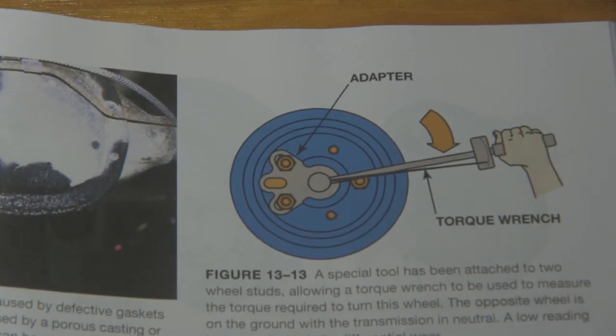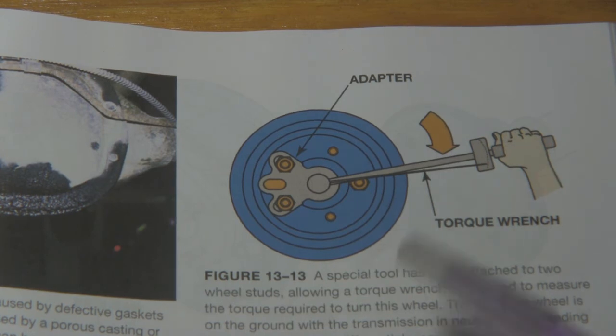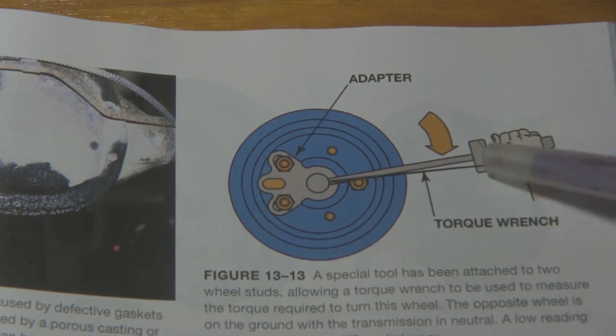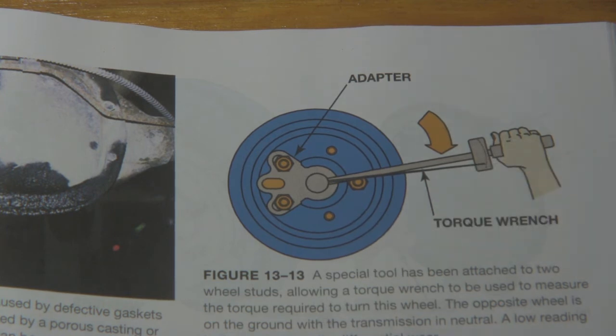Checking for limited slip functionality to see if the clutch packs are good. You can utilize a torque wrench. There are procedures that you can look up in service information. Service information is going to give you a torque spec, and what you're going to do is plant one tire. So this is an axle, so there's another wheel on the other side of this. You're going to put that on the ground. You're going to have this side elevated, and you're going to literally put a torque wrench, a beam style torque wrench, something that you can actually measure rotational force with, and you're going to rotate that axle, and you're going to be measuring the amount of friction that's in that limited slip clutch pack. Too low means that the thing is burnt up, too high means that it's partially engaged. Service information will give you the procedure for that.